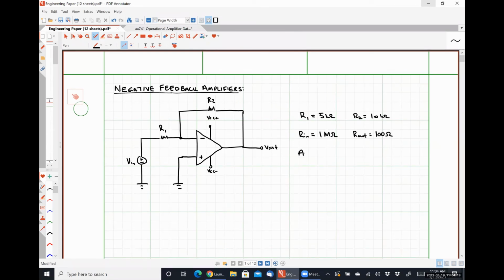And the open loop voltage gain, AVOL, of the op-amp is 10 to the 5 volts per volt. So that would be 100,000. And our input signal, Vin, will be a simple DC voltage having a value of 1 volt. And I'm choosing to use that DC voltage of 1 volt because we're going to be trying to determine several of this particular amplifier's properties.